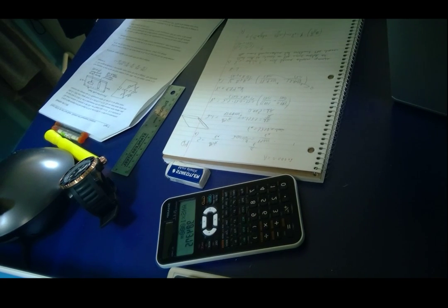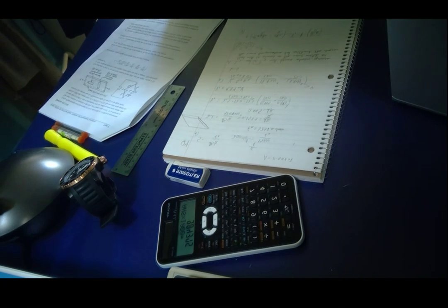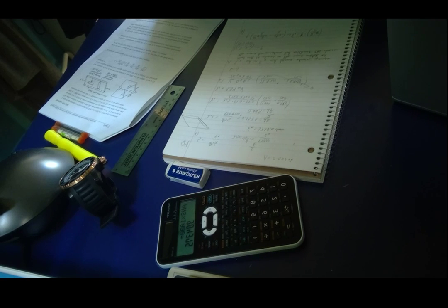D. The strip of high-strength steel is now instrumented with 4 of the same type of strain gauges, so the same gauge factor. The two gauges that are axially oriented continue to correspond to R1 and R3, whereas R2 and R4 are transversely oriented. In this arrangement, find the output of the bridge while applying the same load.